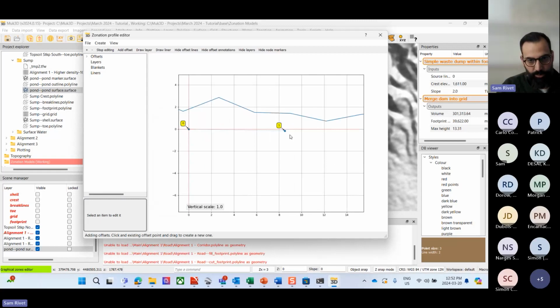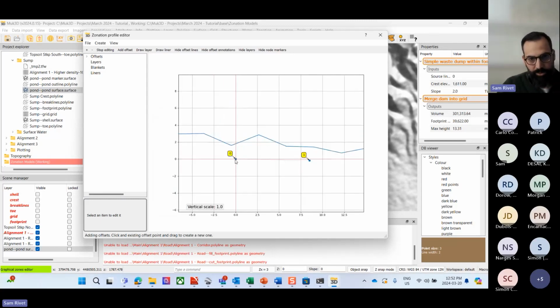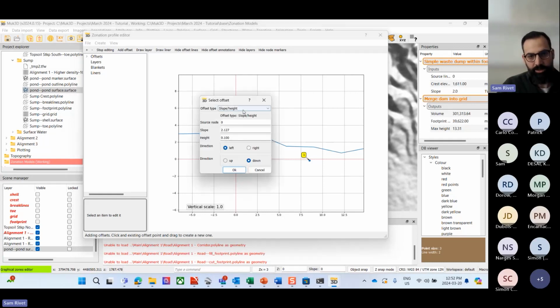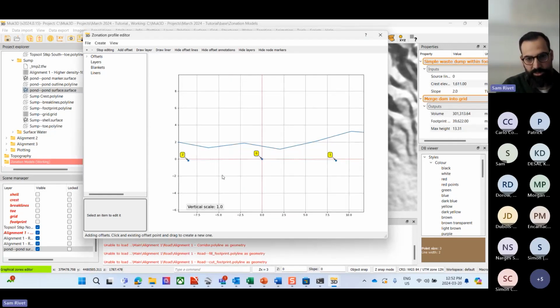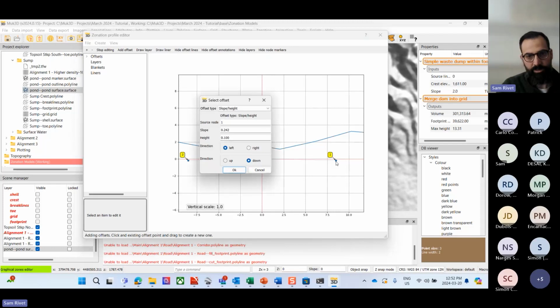Okay, now it's going to add another point here. So now I have a point over here. But I want to reconstitute that top layer crown. I come here. Now I'm going to go dx dy again. I'm going in the other direction now, so minus 8.5 meters, minus 0.17. Okay, and now I'm just slowly building all these nodes. I'm going to come back here to 1.